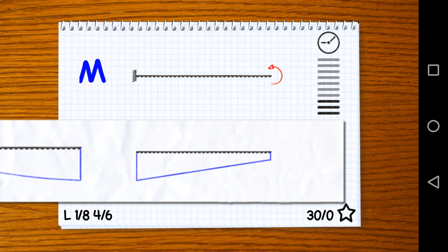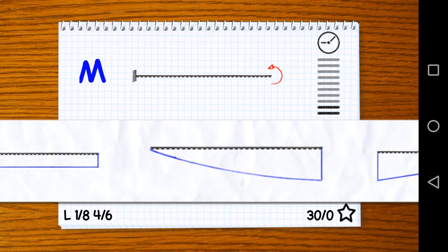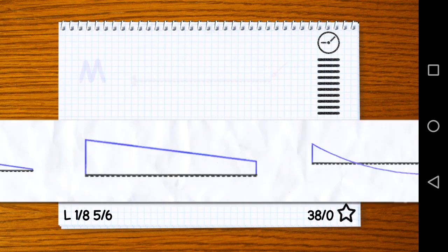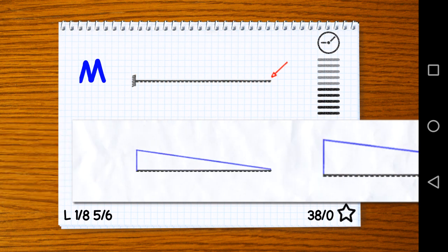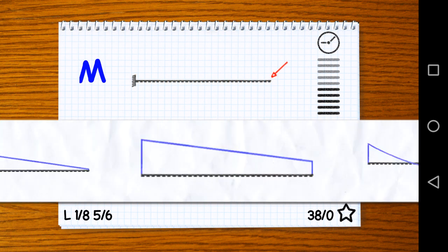We could also cut through the beam and perform a moment equilibrium, of course. So the single load we have here on the cantilever beam at the end of the cantilever beam is gonna cause a bending of the system downwards, leading to tensile stresses on the upper side of the cantilever beam. So the bending moment needs to be on the upper side, so a negative one.